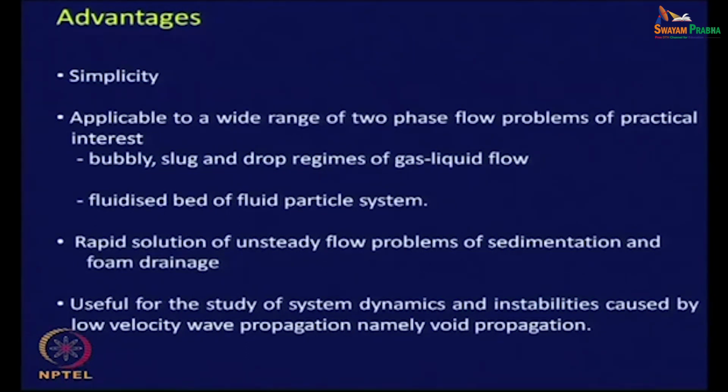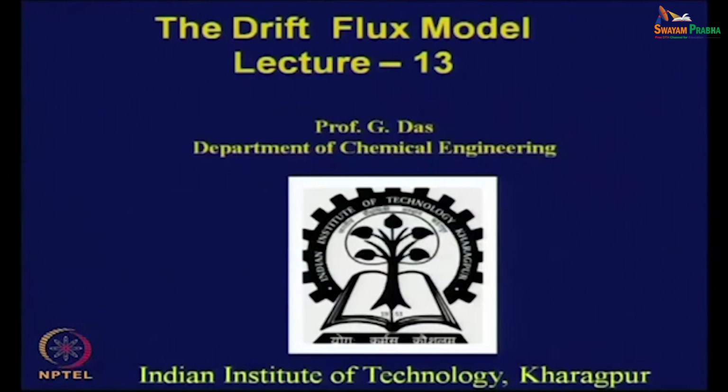Next we find that for rapid solution of unsteady flow problems pertaining to foam drainage and sedimentation, this gives us a very rapid solution. And again, suppose there are instabilities, for the study of system dynamics and instabilities which are caused by low velocity wave propagation, namely maybe a void fraction wave is being propagated, for the study of these things also it is very advantageous. How you will try, you will gradually understand as we go into the details of the drift flux model.